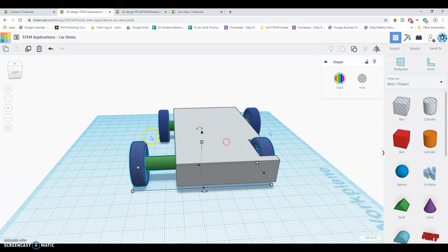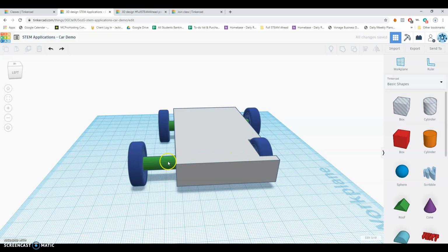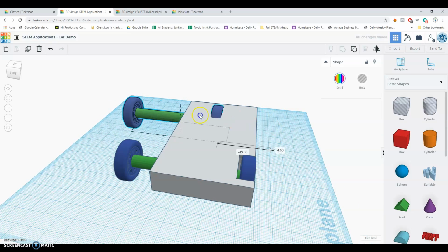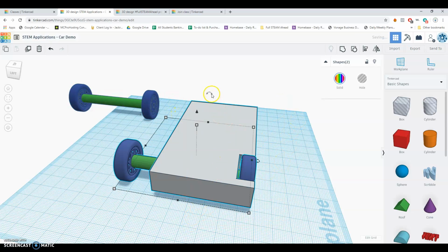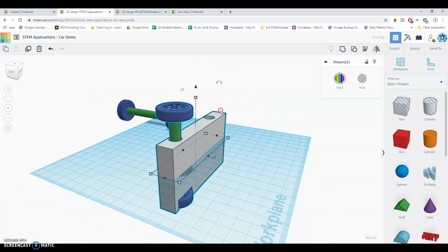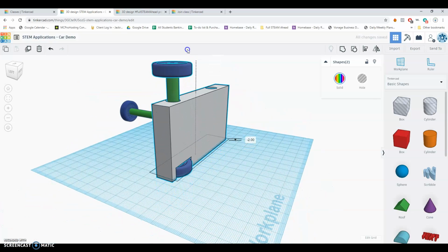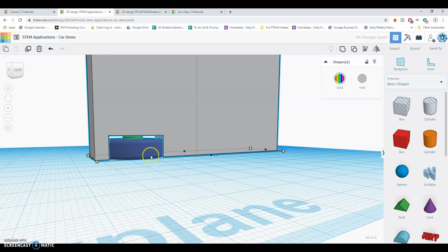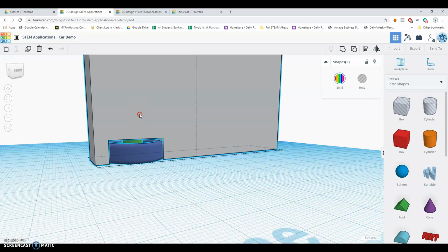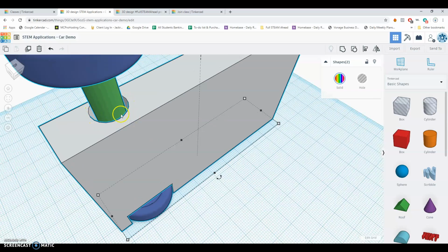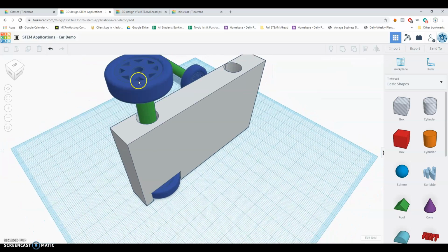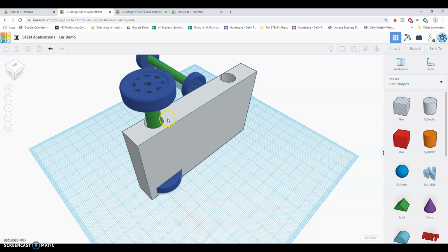So now if I were to do this on both sides, or on all the sides, then I would actually be able to flip this thing on its side. So for example, let me just move these. If I were to do this on both sides, now I could flip this thing on its side, and at least the bottom part is flat, the top part is flat, and I have much fewer overhangs. So now this would print reasonably well. The bottom would be flat, the wheels would be flat. This axle would not be stuck to the inside wall here at all because it would print nice and flat. I would obviously have to do this on this side too, otherwise I'm going to end up with a big mess from the overhang here.